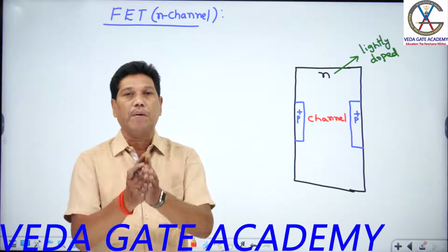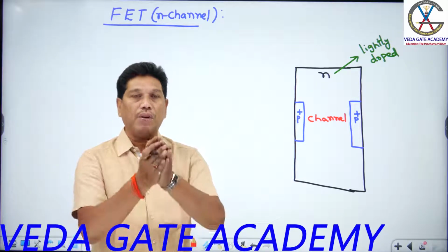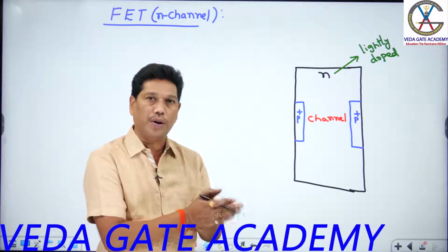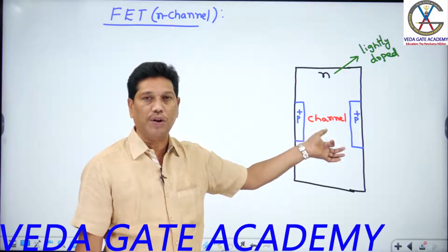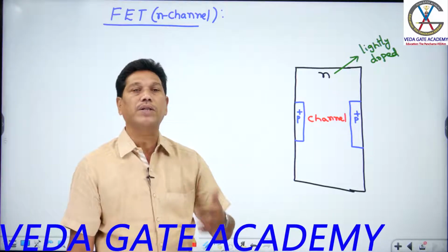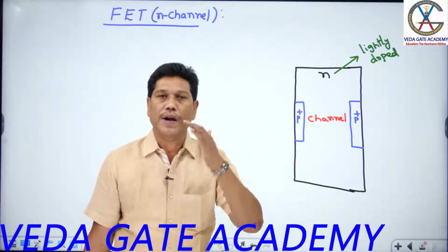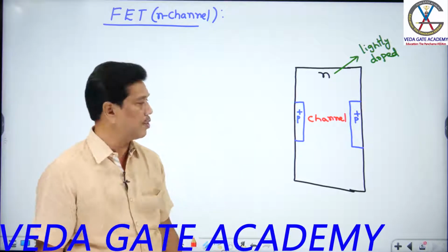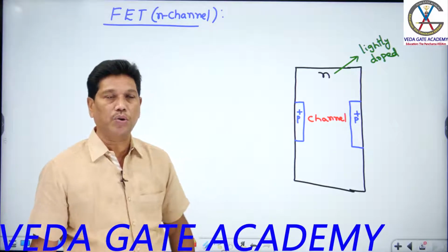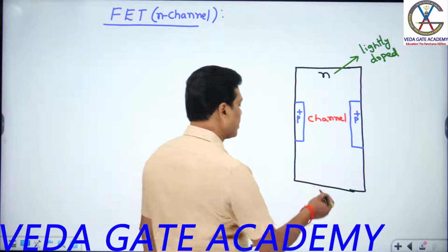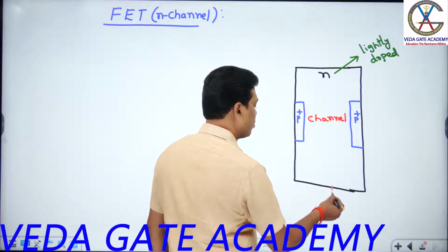The width of the channel is important for conductivity, sir. The channel width is mainly controlled by the input voltage, which you can examine next. So based on that, output conductivity can be controlled by the channel width, which is controlled by input voltage. Based on that, the FET is called a voltage controlled device. Confirm now? And it is a body of 3 terminals. I told you, students, how do you get those 3 terminals? Two of the terminals are taken from opposite sides.